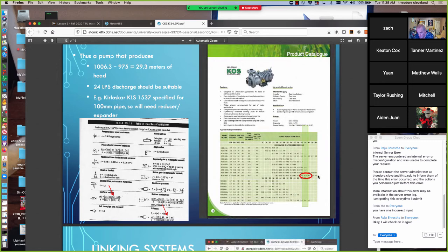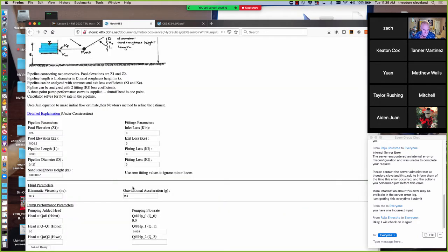We look here, shutoff head is when the pump can't deliver any more flow. So shutoff head looks like it's probably at 38 or 40 meters. I'm going to go ahead and put 40. And I'm looking at these numbers as they get smaller and smaller. This was like a 12, a 6. So 38 is going to be 3. 40 is going to be half a 3, maybe 1.5 liters per second, maybe less. So that's essentially where shutoff is, around 40.